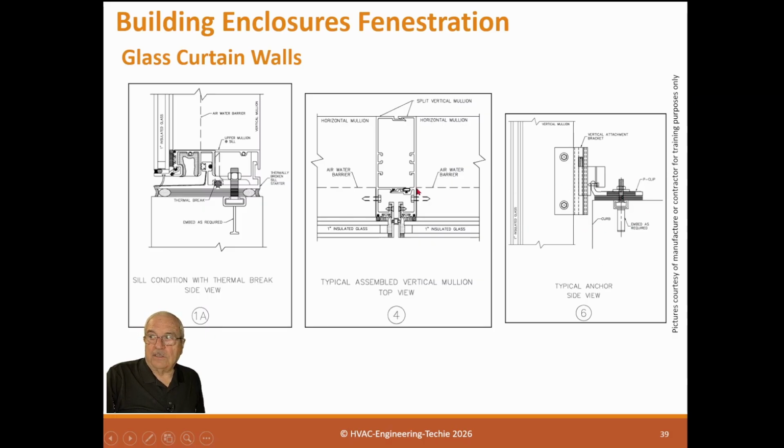It hangs. This is a view looking between two frames that have come together, this mullion. You'll see this is the aluminum frame. It goes together, and then they put some sealant here, and they bolt them together. And this is the glass on the outside of the building. So this is how it goes together. Here's a view of it from another direction. This is the wall, and this is the anchor in the wall, and this is the aluminum frame and how it goes together.